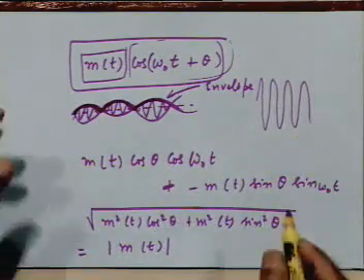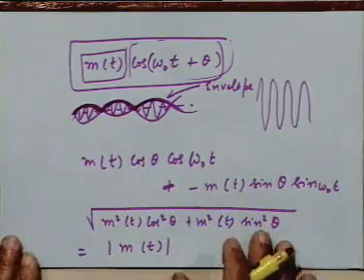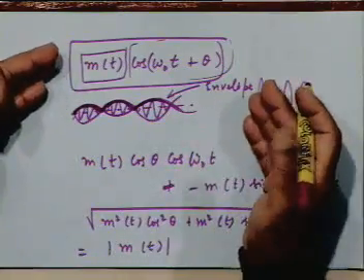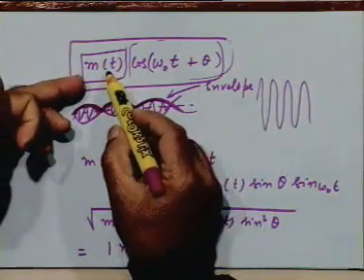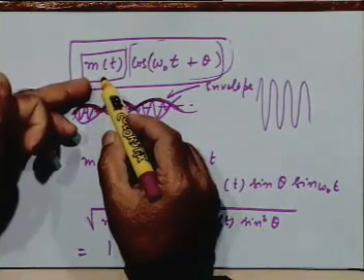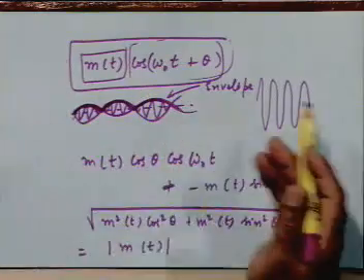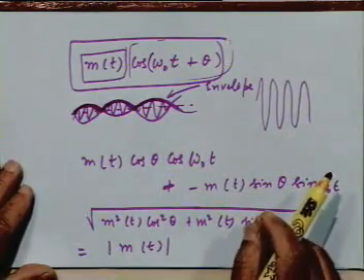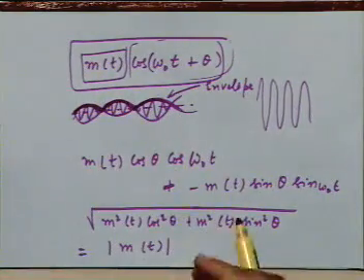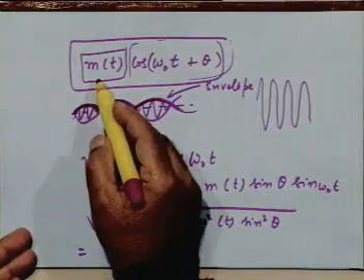So the point that I am basically making is that for bandpass signals of this kind, which is hopefully obvious, because the Fourier transform of this signal will be a frequency translated version of the Fourier transform of m(t), therefore it becomes a bandpass signal. In general, for a bandpass signal of this kind, you can identify an important attribute of that waveform, which you can call the envelope of the waveform, and that contains some useful information about m(t) itself, right?